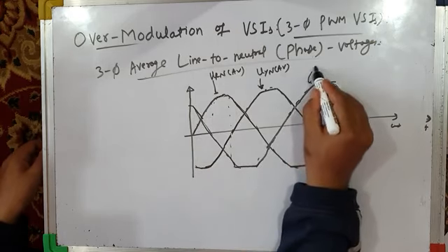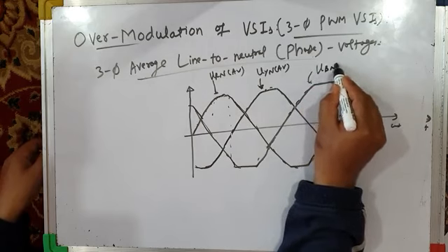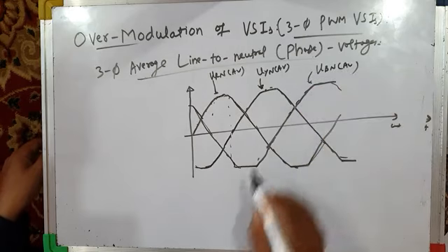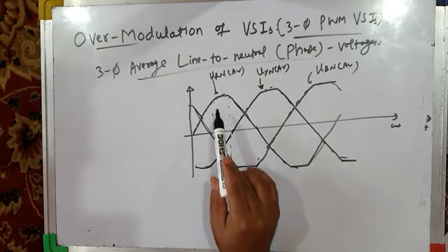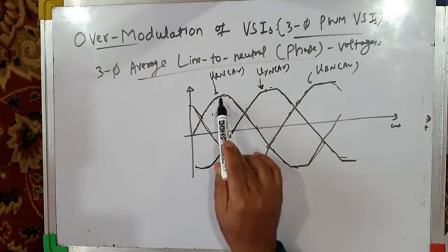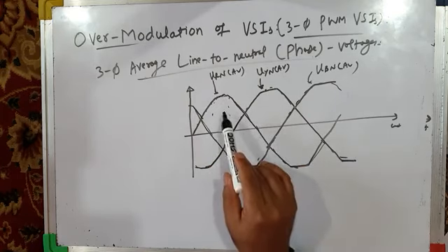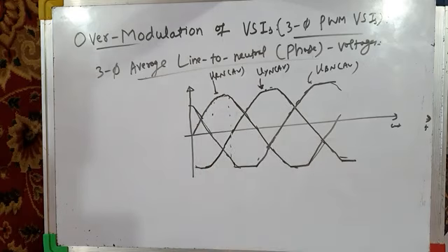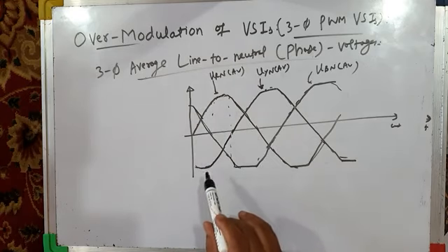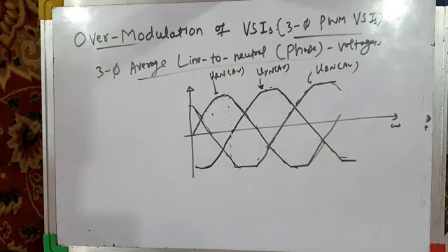This is instantaneous average phase voltage VBN average. So you can very clearly see that the phase voltages or line to neutral voltages also get distorted. They are at low frequency. There is low frequency distortion or low frequency harmonics reintroduced into these phase voltages, and their pattern is similar to pole voltages. Fine.